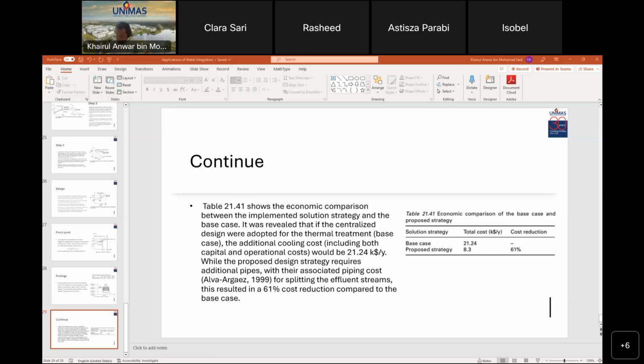The proposed debottlenecking procedure for cooling water system, based on the paper by Robin and Jean, maintains high temperature and low flow rate of return cooling water to increase the heat removal capacity of the cooling tower.